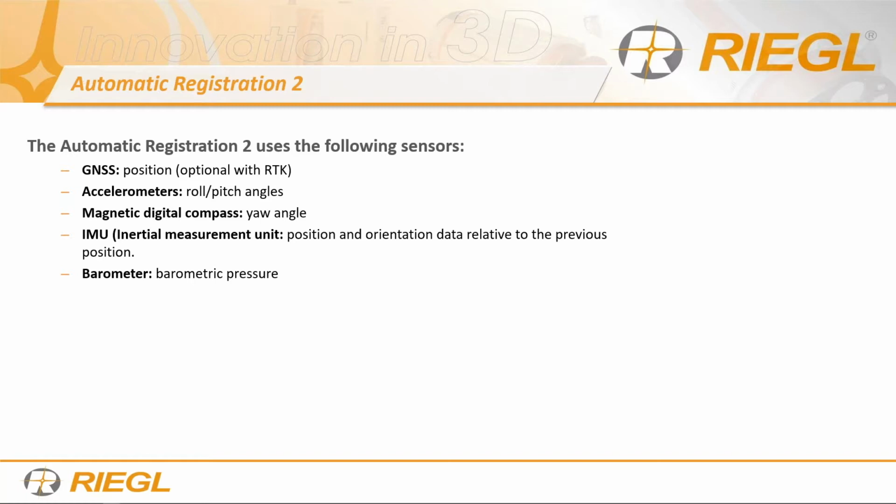I don't know if a lot of you out there know this, we have a large crowd today. You don't have to level the scanner, right? You have to put it within a certain number of degrees. I think our specification is like 10 degrees, something like that. But as long as you have it upright, this information is very useful. And then the IMU gives you the orientation, roll, pitch, and yaw.